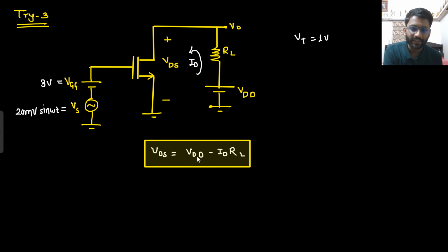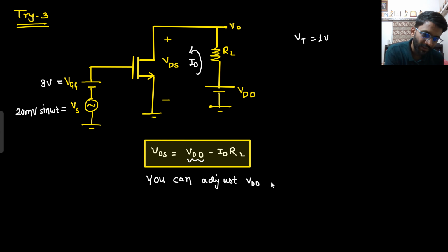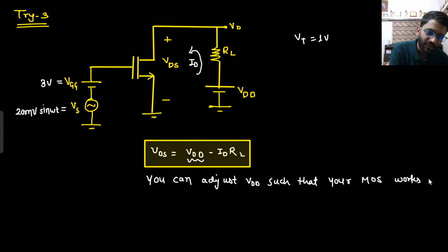Now you can adjust VDD. You have the liberty to adjust the VDD such that your MOSFET works in saturation region.